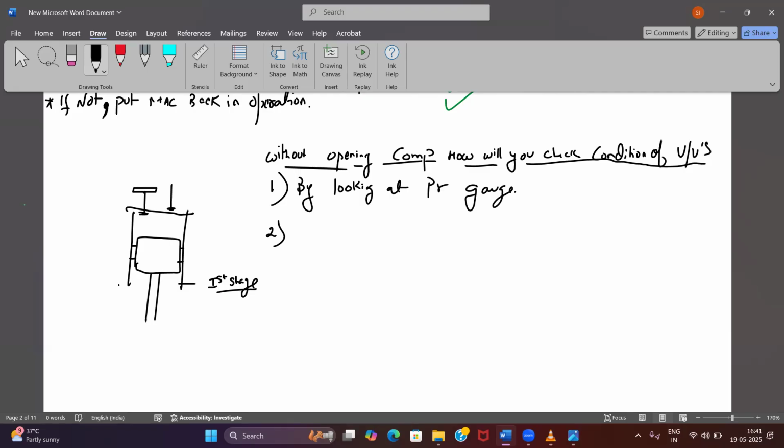Sir, we will turn the flywheel slightly by hand from the back. Very good, we can turn the flywheel, and you should feel the suction on your palm. If the piston moves down, it will create vacuum here. Sir, it is done with a tommy bar, right? Tommy bar se you will try to move the flywheel of your air compressor.